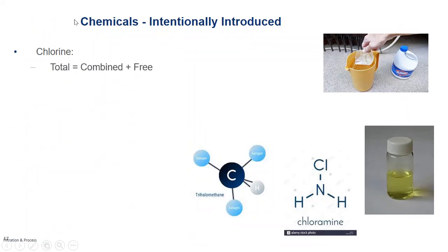And you'll get free chlorine reacting with combined chlorine until you break down the organics into either chloramine or trihalomethanes, or until you can break these down even further. This takes a lot more oxidation to break those off into regular methanes and gas off. But chloramine is something you're really familiar with. You think of it as that swimming pool smell.